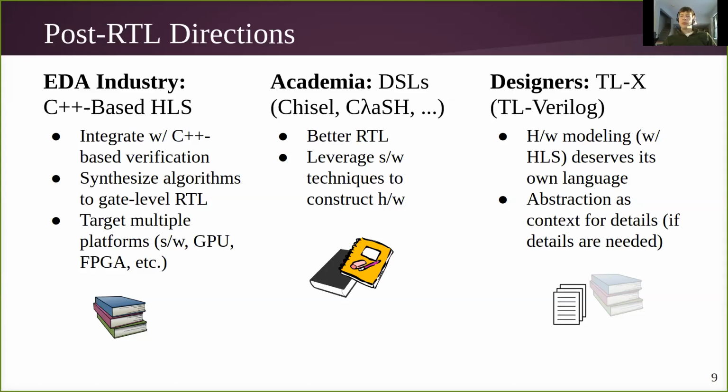And transaction level modeling, where a few very simple constructs, some of them you'll learn today, some you won't, layer on top of existing languages, Verilog in particular, and really obviate the need for a lot of the Verilog language specifications.